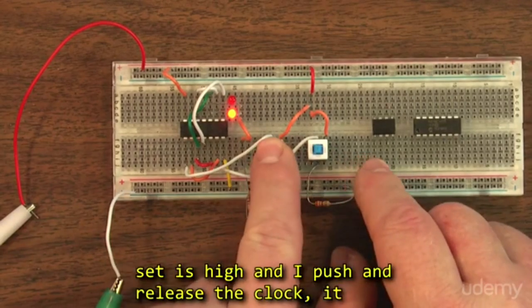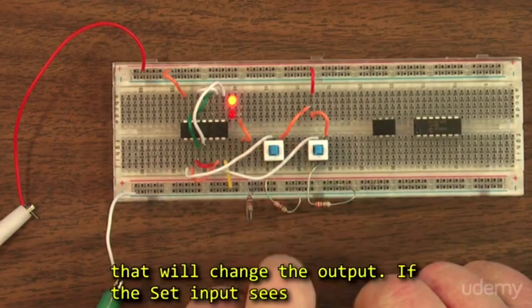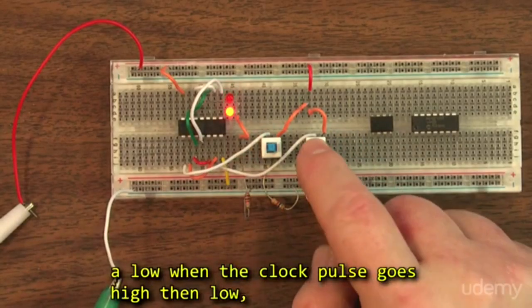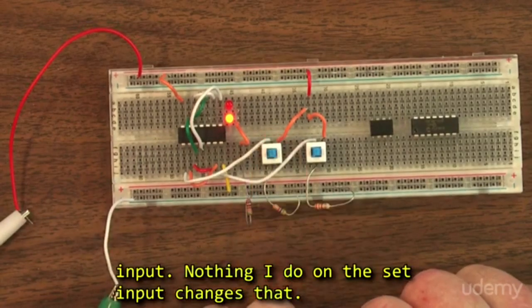If set is high and I push and release the clock, it stores the high on the output. Nothing I do after that will change the output. If set input sees a low when the clock pulse goes high, then boom, it stores the low it sees on the set input. Nothing I do on the set input changes that.